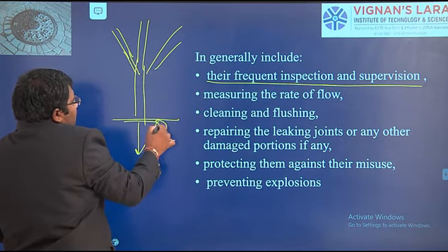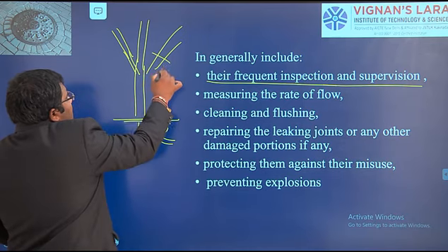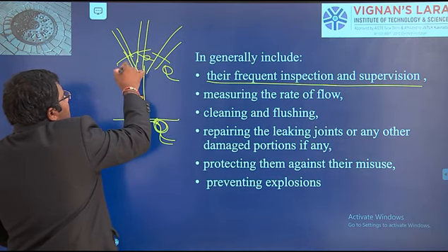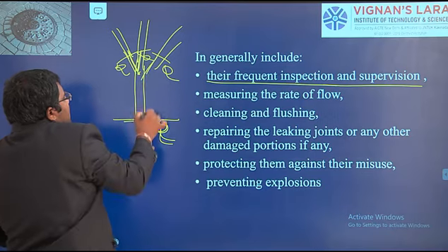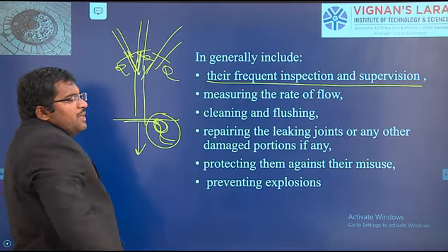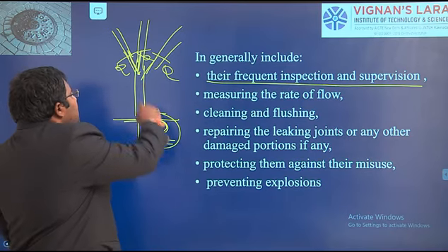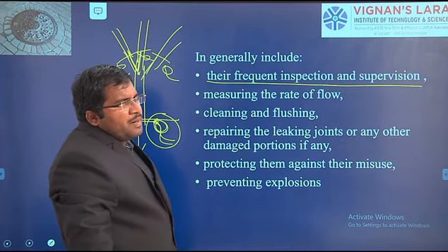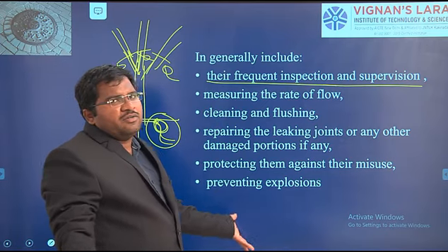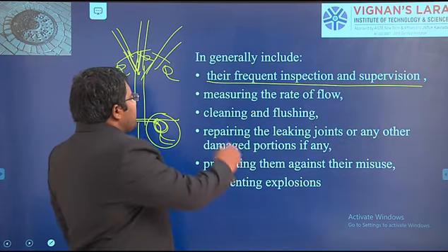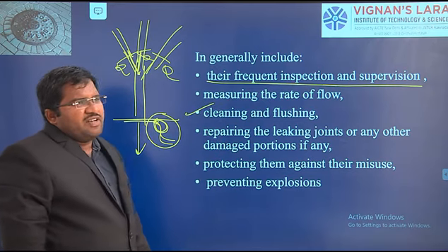Here we will measure the discharge, here we will measure discharge, here discharge, here discharge. By combining all discharges, the total amount has to be the same. But if there is a difference, it means some problem is there, and we have to get it repaired or cleaned. Next, we have to go for cleaning and flushing.